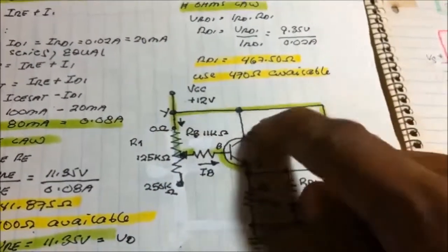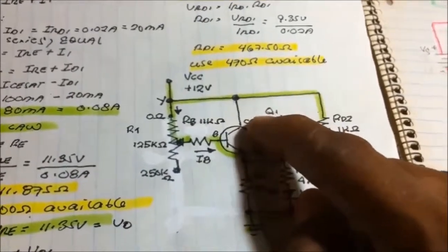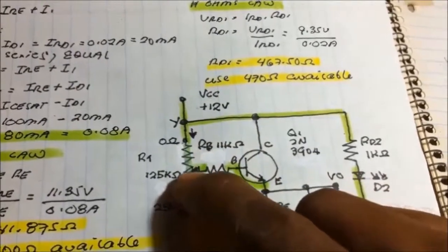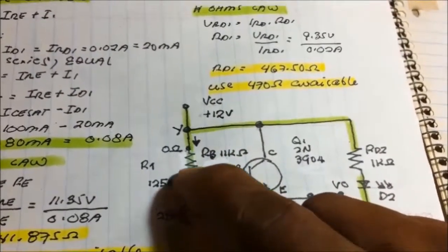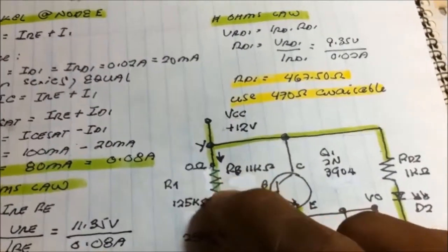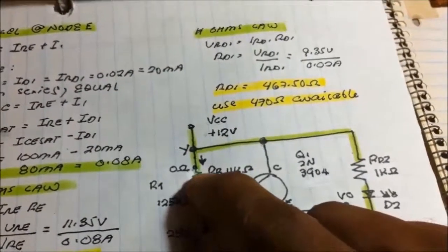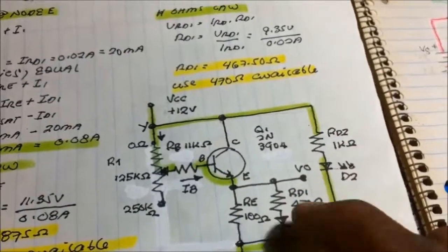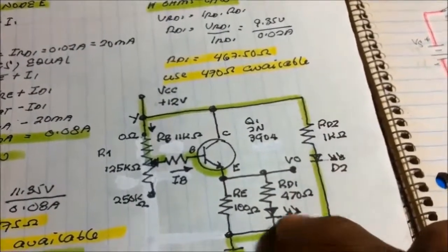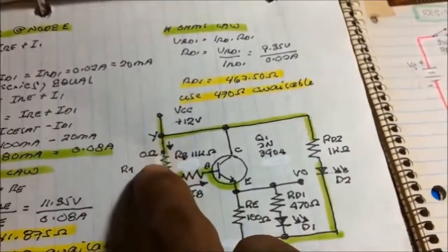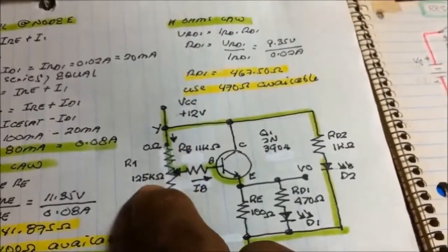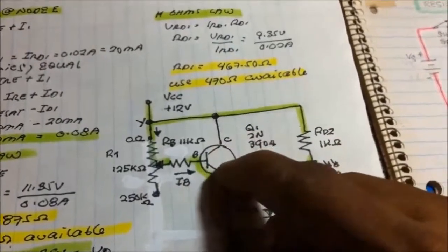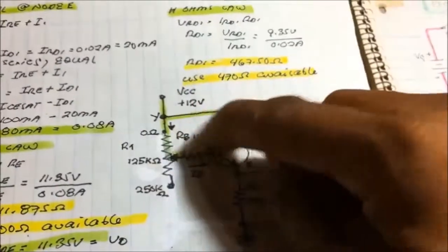This makes the transistor in cut off. As you increase the resistance little by little, it decreases the brightness of the LED until you reach 125 kilo ohms. That makes this transistor operate in cut-off. Almost no current flows.